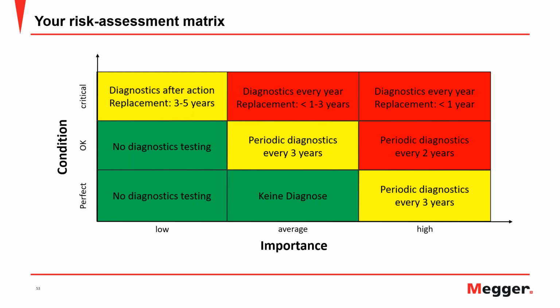If you say, no, it looks bad, but I don't want to take action immediately, then you have to do at least repeat measurements frequently to see if you're running into a severe deterioration of the splices that you saw PD activity in. So that is pretty much the level of the asset manager, that this is eventually what you create, what you have to come up with.